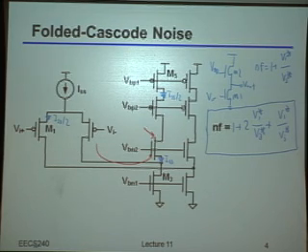Okay, so now let's go back. Well, actually, let's even look at this picture. If I look up into that stack of PMOS transistors there, how high is the output impedance? Roughly speaking, in terms of gmro, let's not ignore the 1 plus just because I'm lazy. It's basically gmro squared, right? Well, if that is gmro squared, that's implying the swing up there is like gmro squared times the input